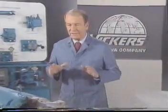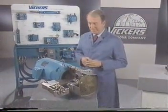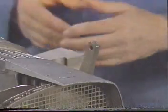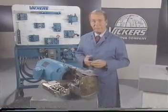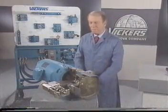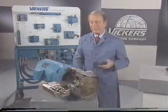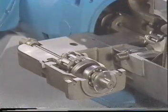For a more realistic view, we have a cutaway of a complete package including the electric motor which drives the pump. This lever controls the yoke, which contains the swash plate, enabling us to control the amount and direction of pump flow. This in turn determines the speed and direction in which our motor rotates. Flow paths interconnecting the various components are cast or drilled into this section, combining everything we've discussed into one integral unit.